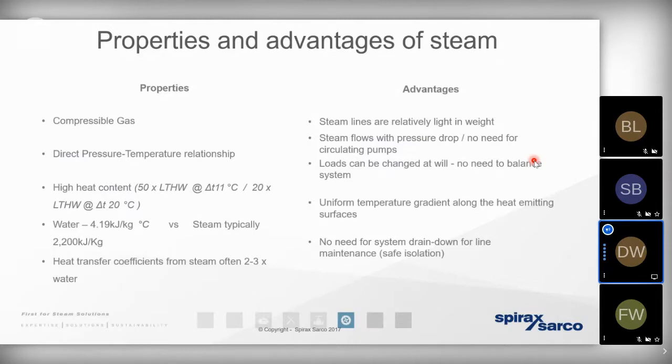And other properties of steam make it a very advantageous source of heat energy for heat transfer. As we've mentioned, it's a gas. That means that it gives up its heat energy equally and evenly across the entirety of the heat transfer surface area, meaning we only need very small compact heat exchangers, reducing the footprint of space we need to set aside for a heat exchanger.